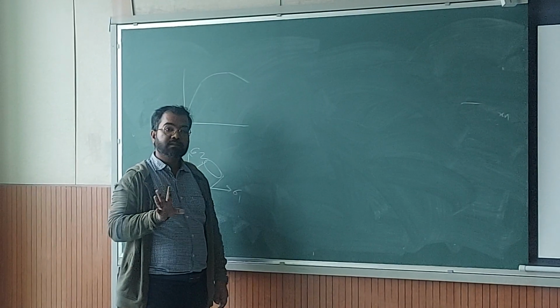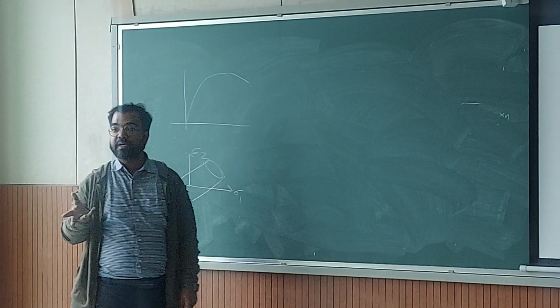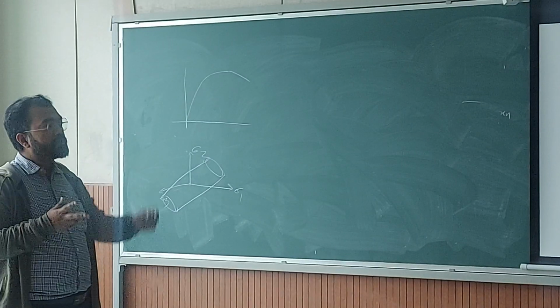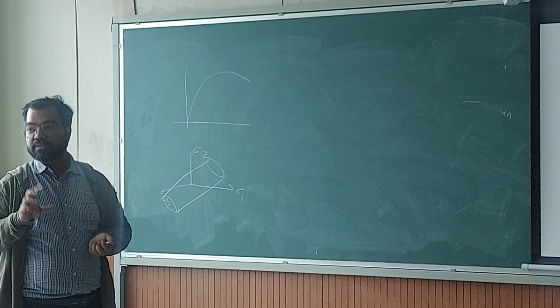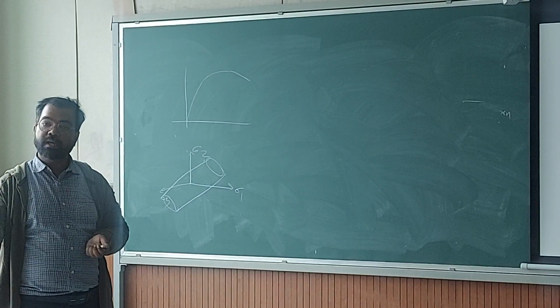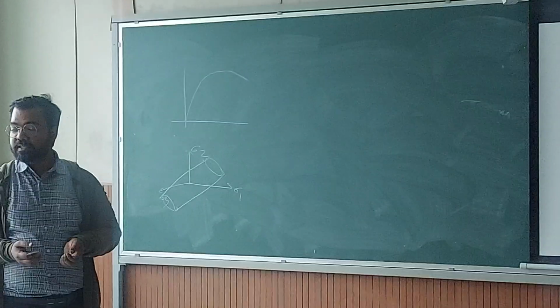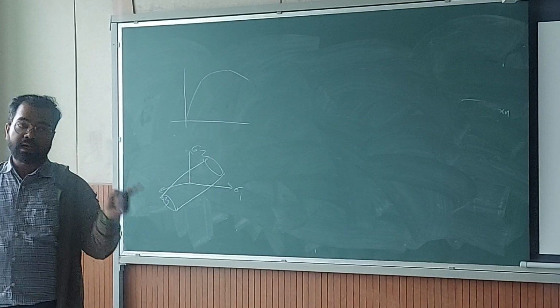With those errors, we have to deal, and we have to take the kinetics of omega. So if you do that resistivity experiment, you find the kinetics of change of resistivity, relate it to omega, put it in the formula, simulate it for your tensile specimen, and then you match the load displacement curve for your experiment and the finite element analysis.